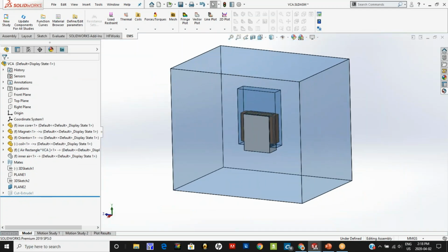The first thing that I will bring to your notice is the concept of the air geometry. To do any magnetic simulation, we need to be able to calculate the movement of the magnetic flux. Obviously, it moves inside all the solid materials present in your model, but the magnetic field is also propagated in the air around the model.